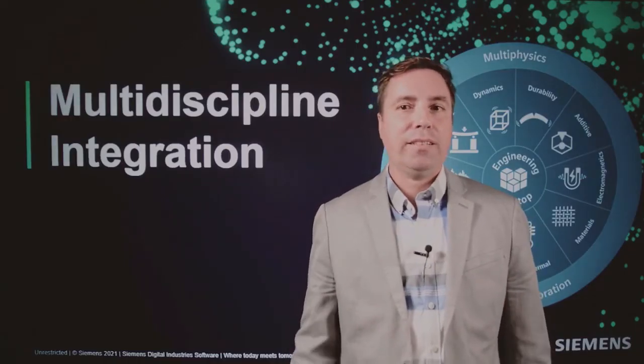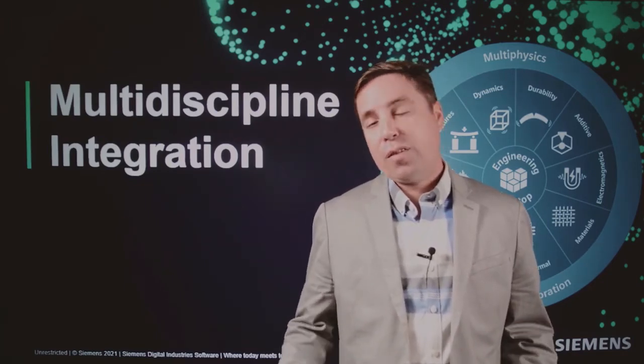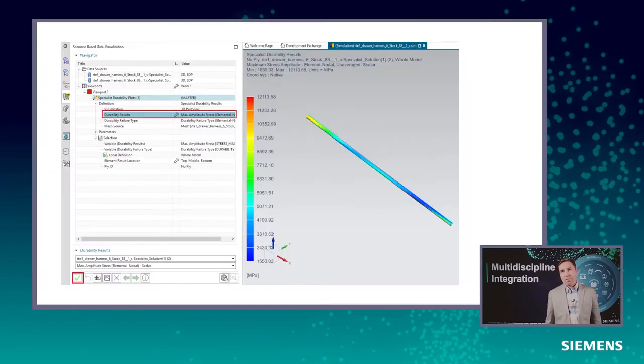But because hoses like these are constantly moving and getting cycled through various positions, it's important to determine the expected lifespan of hoses or cables, including their connecting elements, through fatigue analysis. In this release, the stress tensors from Simcenter 3D Flexible Pipe modules can be available as input into the Simcenter 3D Specialist Durability Solver in order to predict fatigue and failure. This completes the full design loop, as product life is an important criterion used to evaluate the best hose and cable design to avoid product recalls.